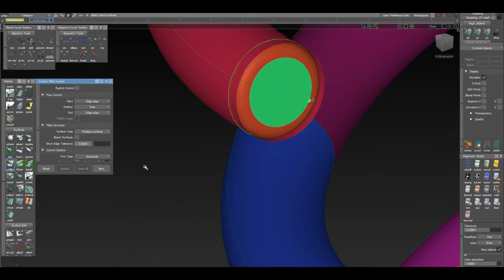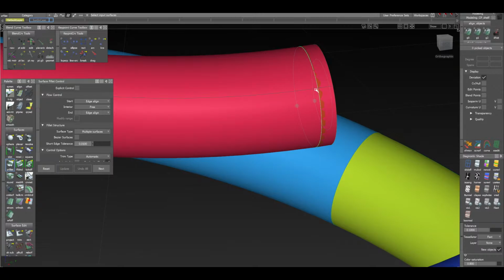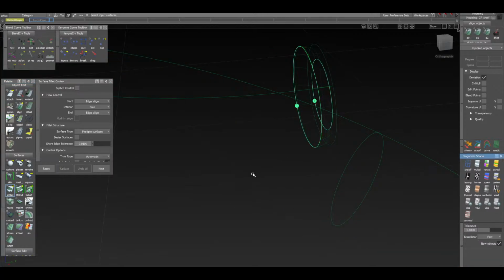And what I'm going to do is a bit of a hack here. I'm going to create a planar on this back edge over here of the fillet, and I'm going to untrim that planar. With that untrimmed surface, I'm going to use it as kind of like a slicing tool to slice through magenta over here. All right. So, a handy little way. You know, in Alias, you're always looking for workarounds and hacks and stuff like that. It's just kind of the nature of the beast, you know.